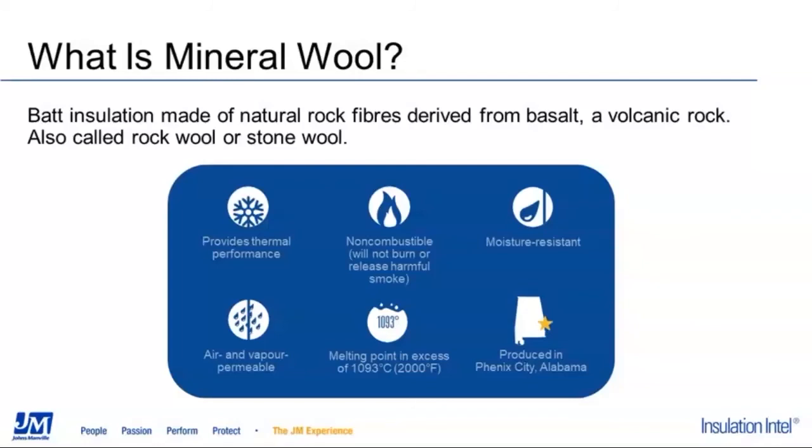A lot of our competition who do mineral wool only have historically done a very good job of promoting the sound performance characteristics of mineral wool. And mineral wool is a fantastic sound attenuation product. It does a very good job, but the reality is when fiberglass and mineral wool are installed to the same density in a similar type of wall, they perform the same. The human ear cannot detect the difference. So while there is the notion out there that mineral wool is a superior sound performing product, in our experience, really fiberglass and mineral wool perform the same. So that leaves you really with the main advantage of mineral wool being where fire performance is required.